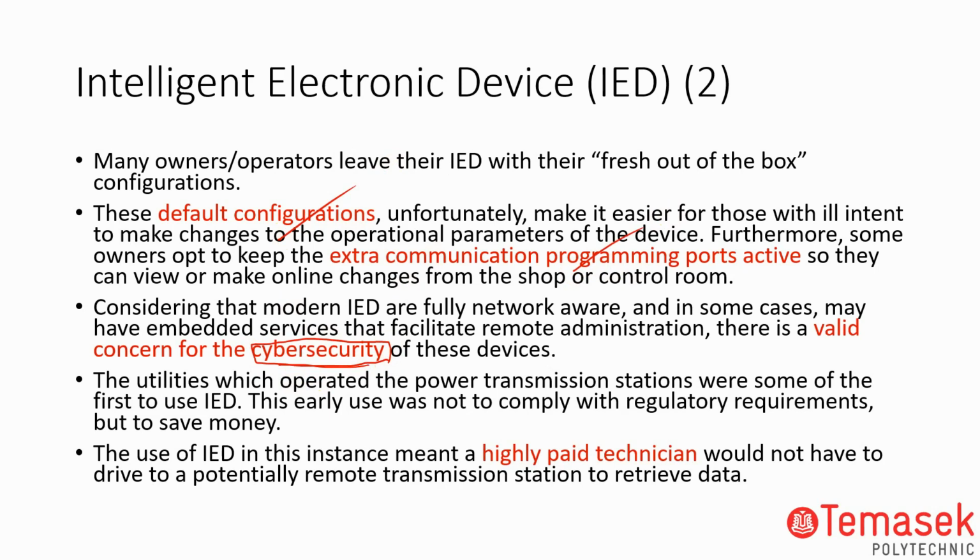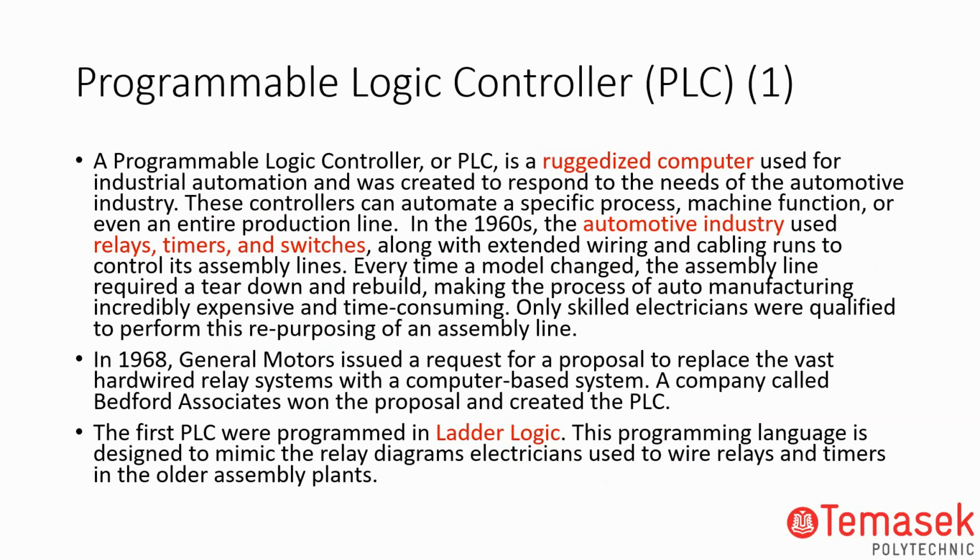So IED is mainly meant for high-paid technicians, so that they do not have to drive potentially to the transmission site to retrieve the data. A lot of the time they do remote access. They plug into the RTU to do remote access and everything. So there are terms and conditions on how to go about doing this, but it is important that the cybersecurity takes place over here. This is one of the more important portions.